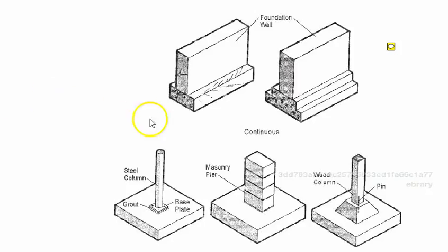What this diagram shows is a couple different types of shapes of concrete. A continuous footing that you'll see under a foundation wall, or isolated footings that'll be pads under, say, a column. This might be the kind of footing that's done under, say, a fountain. And this would be under a column somewhere, although you have to check the plans to make sure you know what you're using. But you're going to use wood forms or steel forms to make these shapes of concrete.